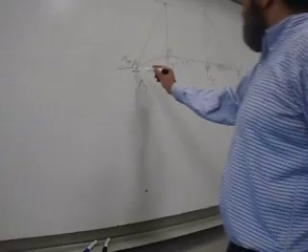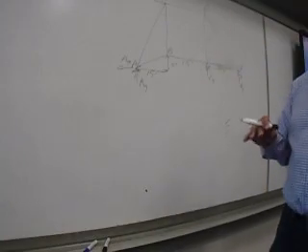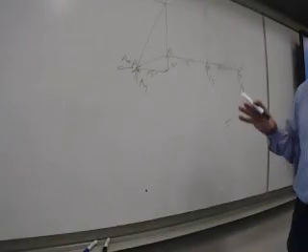What do I have here? That's 15 by the horizontal distance here. Okay. So you are saying it's indeterminate? Bravo. Why do we have a geometric instability here? We're missing a member. There's a missing diagonal here. So this missing diagonal, watch out. This is a very special case.